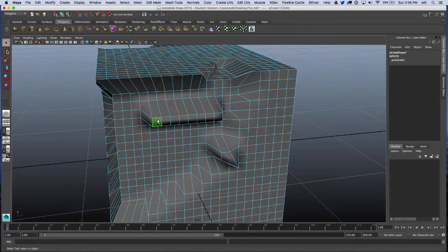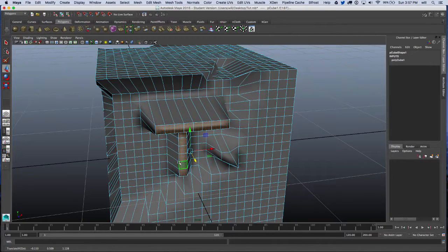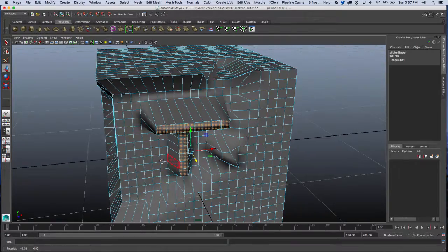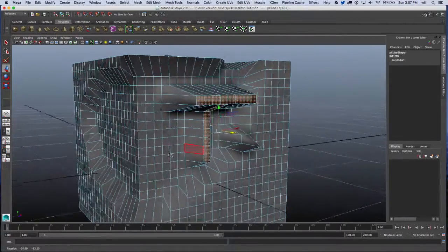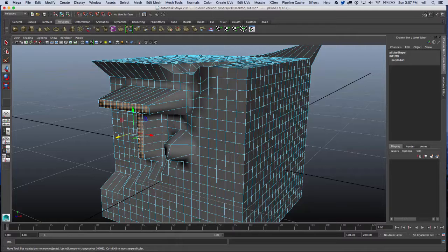So if I have this, I can select from here and hold Shift and then double click, and it'll select all of the faces for me. That also happens when you select this again and double click. It'll select those faces. Then I can use my move tool and move those faces together. Again, holding Option and dragging that around. This is the interface, just moving faces and or vertexes.